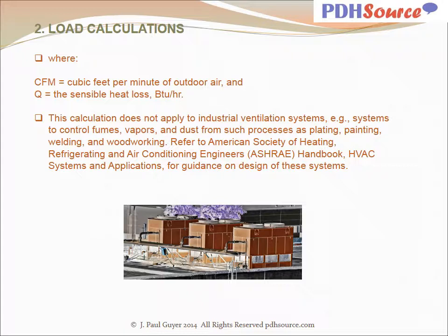This calculation does not apply to industrial ventilation systems such as shops and things like that where you are intentionally exhausting large quantities of air from the inside of the building, like through fume hoods or paint hoods, things like that.